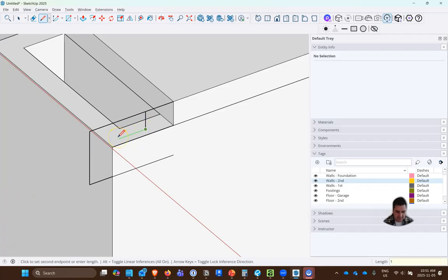The one thing about exterior stairs is you can actually change grade. So you could just say the stairs are 7 inches, and then you can just slightly lower the grade with, you know, a shovel, technically, right? And so the exterior stairs are kind of cool in that way. We have a little bit more flexibility. So we'll go down 7 inches. And it looks like the steps may be a bit longer, but that's fine.